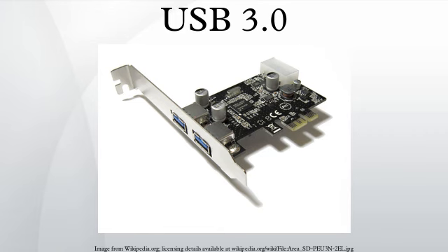All major test equipment vendors offer tools for testing devices and cables against USB 3.0 electrical compliance requirements. Electrical testing requires a USB 3.0 test board providing Type A, B, or Mini-AB electrical compliance test breakout adapters. A factor affecting the speed of USB storage devices is that the USB mass storage bulk-only transfer protocol drivers are generally slower than the USB-attached SCSI protocol drivers.